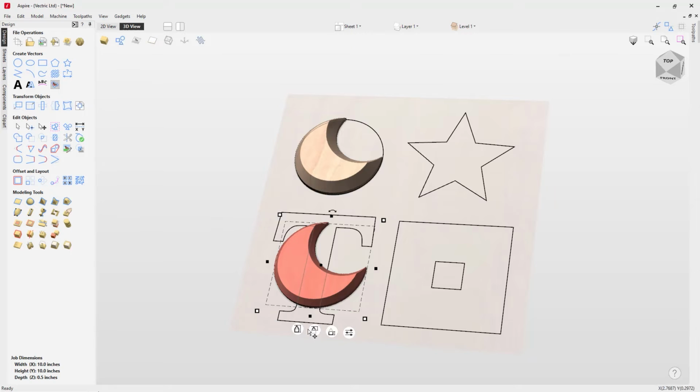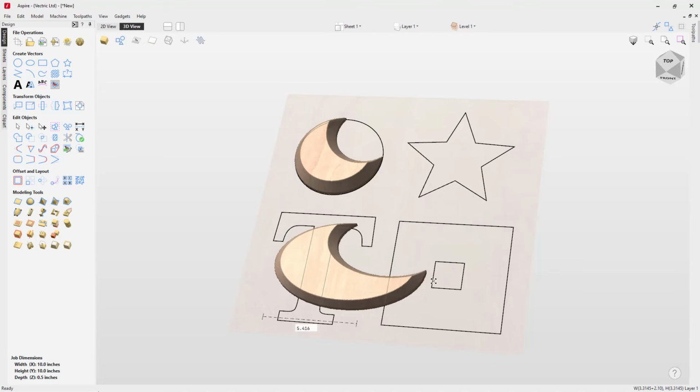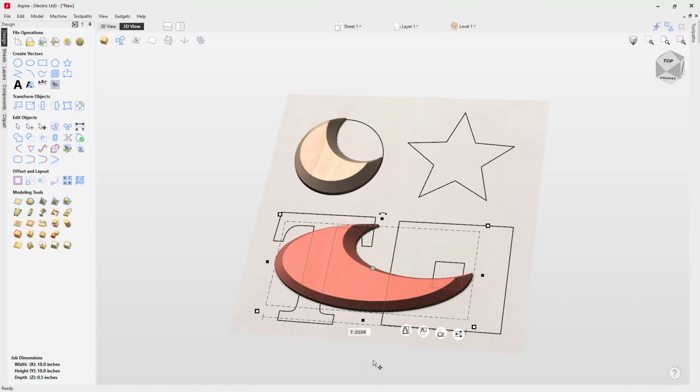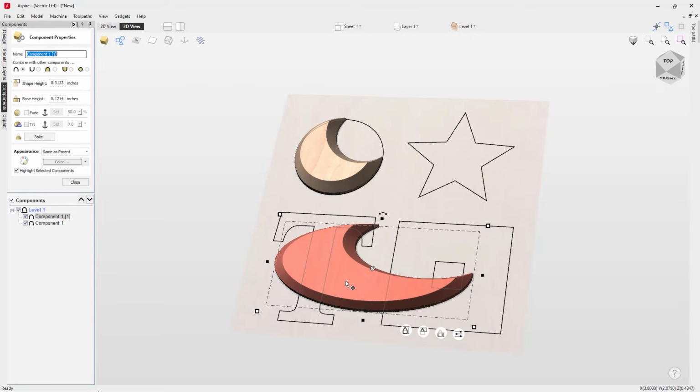The only time where we won't be able to access the create angled shape or any of the tools that we use to actually create that is if we altered the component by adjusting the transformation of it. So if we stretch that out, and now if we press E on the keyboard, you'll see it just takes us to the component properties tool, because we've totally taken that out of its original primitive shape, and so we no longer have access to edit the additional handles that we saw in that angle shape form, where we can adjust the angle, the limit, and dynamically make those changes.